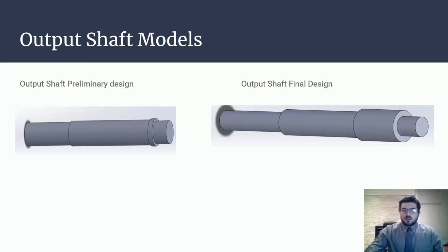The ends are where the shaft will go out, so those are a little arbitrary. The important parts are closer to the right of the shaft on both sides, and as you can see, the step had to be greatly increased. The size of that first step had to be increased due to the diameter being decreased from our iterations. This was the shaft that actually saw the greatest reduction of mass due to the critical speeds being the quickest.